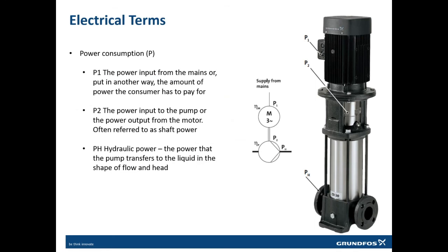Now, in electrical terms, we need a motor to run the pump. Whenever we talk about pumps, whenever I discuss with some people, we always get confused about the different types of power. In a pump, we have 3 major powers. The hydraulic power is the power of the water, with some amount of water, with some head, generated by the pump. This is calculated by rho g Q H. Very simple, by flow and head.